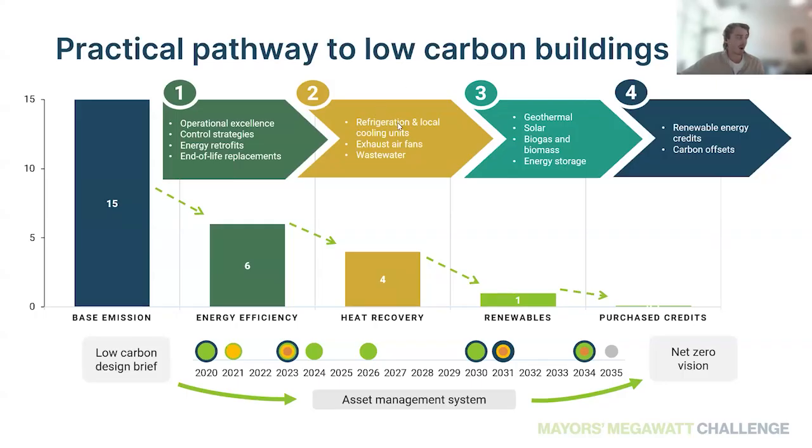But outside of hockey arenas or grocery stores and data centers, there's also just typical exhaust ventilation heat recovery. Heat recovery ventilators and energy recovery ventilators capture any and all of that waste heat to improve the overall building efficiency.